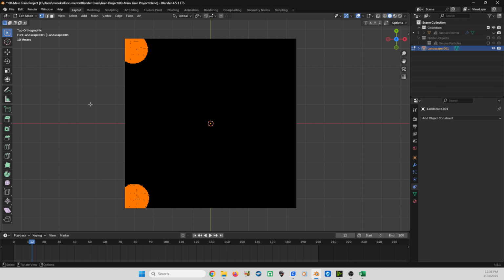and let's switch. I'm going to hit enter to confirm that, but let's switch to wireframe because you'll notice that I'm not getting all of the vertices because some of them are hidden a little bit. So switch to wireframe, then we'll hit C again to bring back the circle select. And now you can see that when I click, it selects all those.